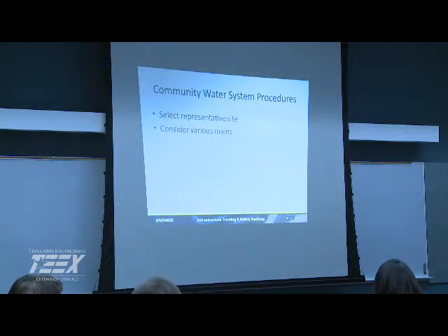In a larger system, like municipalities, there are GIS departments. There are some really neat interactive maps you can pull up and look at when the valve was made, the size of the valve, the manufacturer of the valve. If you've got the money, there's somebody out there willing to build you a system. Especially on the large ones, they've got some really neat stuff. But even as a small system, even if you just have a few taps, having a good understanding of what your main size is and where your laterals are located is not that expensive, and you can incorporate some of that technology.